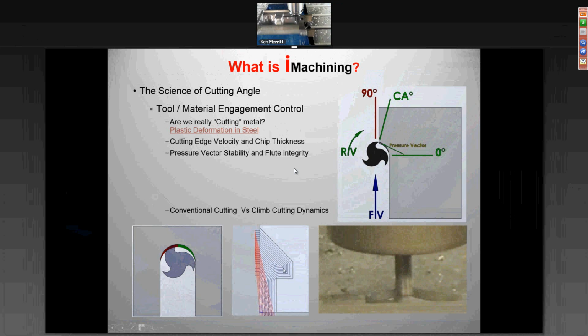When we get into a traditional style of toolpath pattern where it's just an offset toolpath, you'll notice they have these sharp direction changes throughout the entire operation. I like to call these compression zones. They're kind of an area where we wind up overloading the tool and creating very negative forces on the tool. In these conditions, we wind up seeing the tool in what we call a full width of cut.